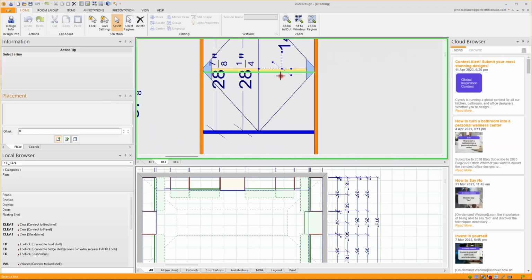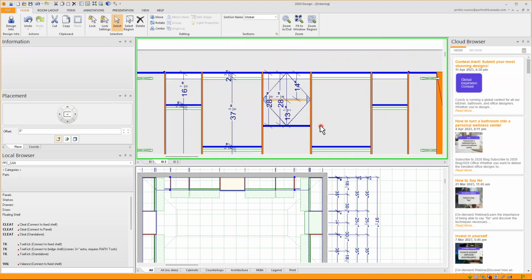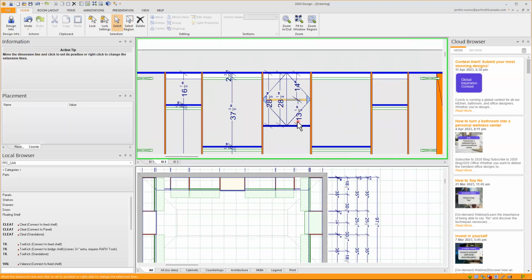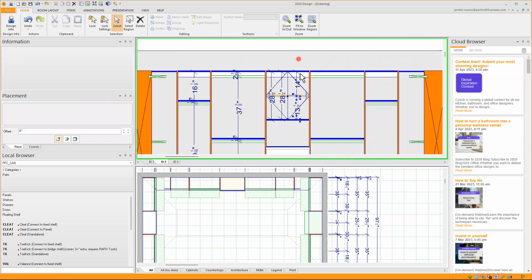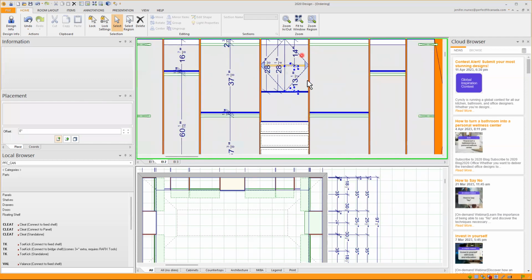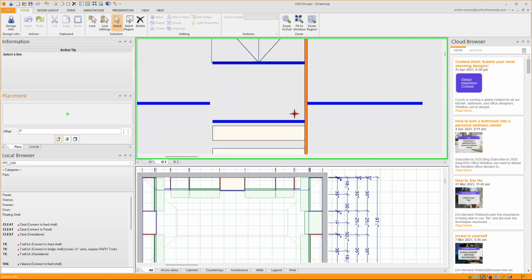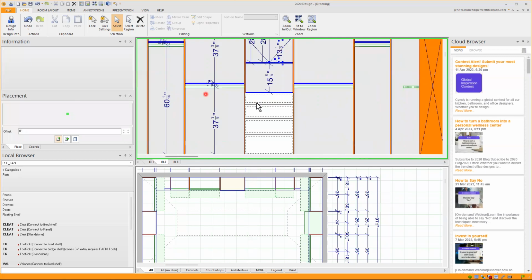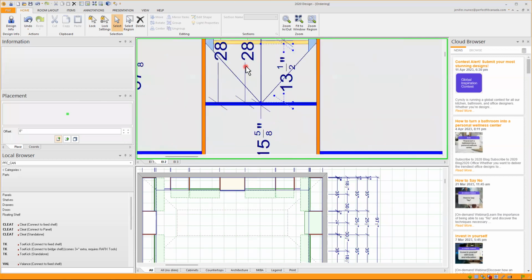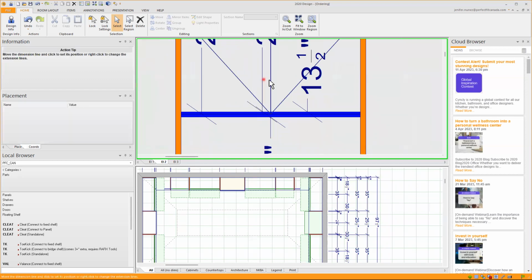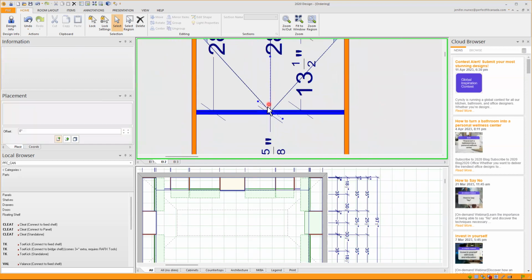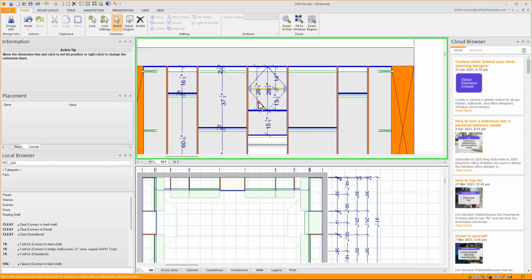So here I have this adjustable shelf. Oops, I'll click outside the drawing and go back there. Okay, so between my shelves, I have 14 inches on one side, in the upper section, and 13 and a half. That's perfect there. And here, this opening is 15 and 5/8. I can move this one here just to leave the openings in the center.